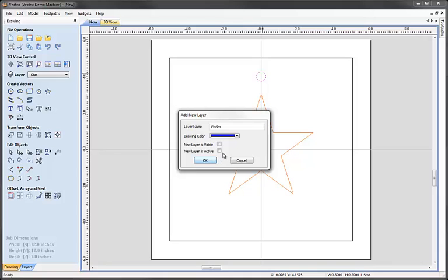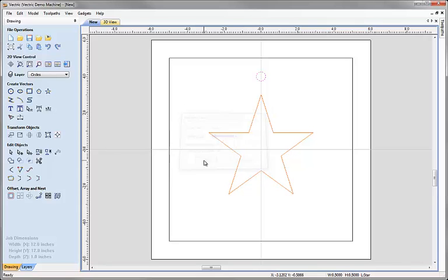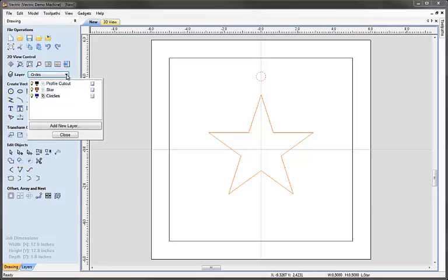disappear. In my case, what I'd like to do is make that layer that we're creating both visible and automatically make it the active layer. So when I hit OK here, you should see the name that we've got up here change to the layer that we're creating because we've asked the software to make it active. So if I click OK, we can see that name's changed up there. So now my currently active layer is this one called circles. If I click on the drop down, we can see there that that is the one that's shown in bold.